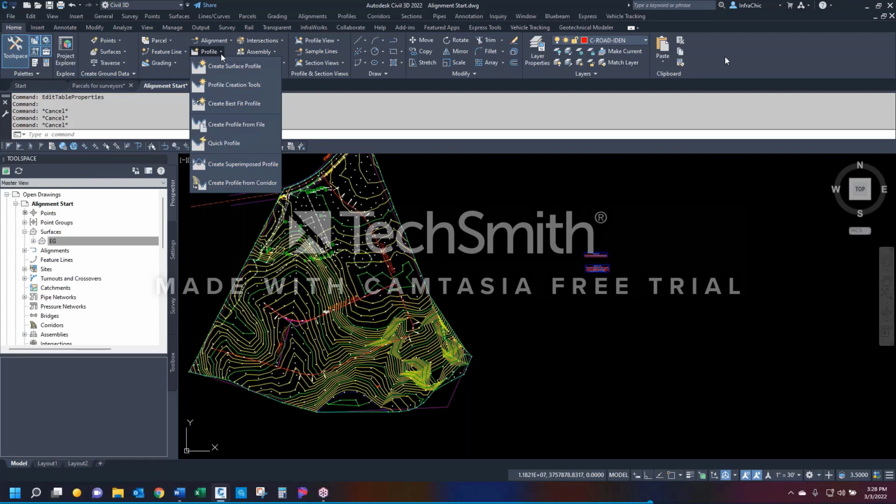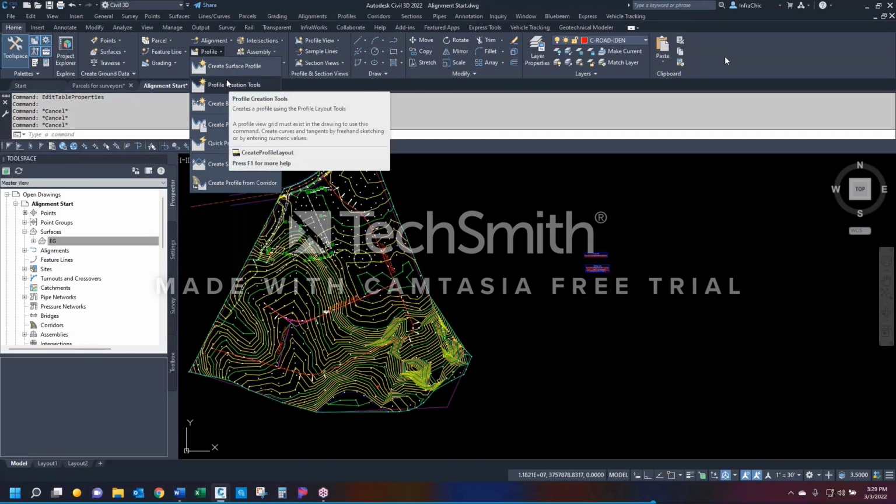Now, I will say this, Profile Creation Tools works identical to Alignment Creation Tools, but only inside the Profile view. So it has lines, it has curves, it has sub-entities. You could draw all you want to your heart's content. If your alignment stationing changes, your profile is independent of that alignment stationing. If you made it from Creation Tools, it's independent. It stands on its own. So if you moved 1,000 feet, your profile is still back here at the original stationing.